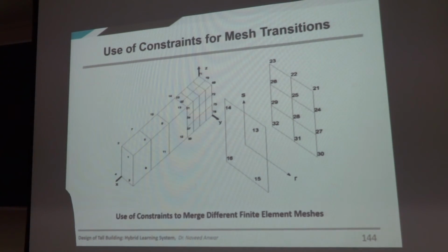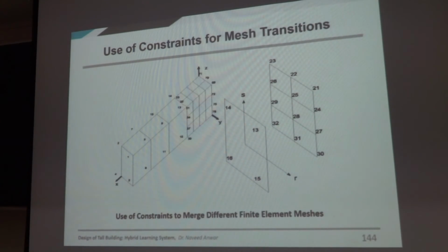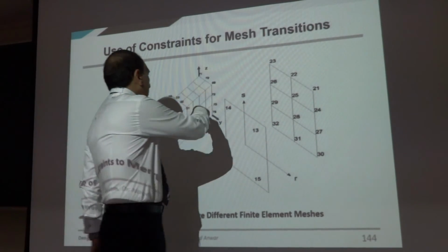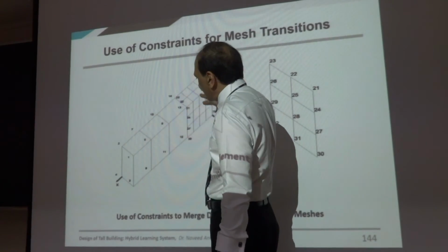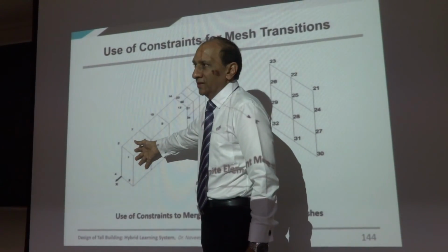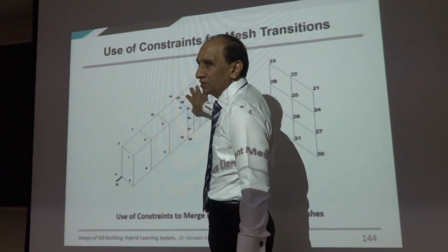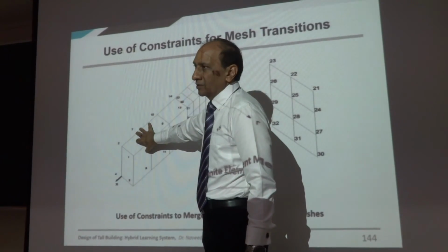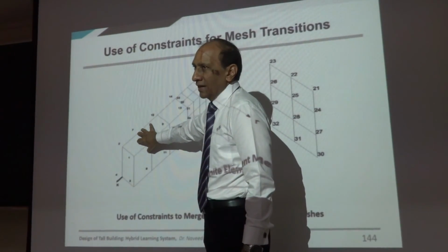So I chop it up into small pieces, Lego pieces, because I want to understand what's going on inside the beam. Not only the overall bending moment, I want to calculate stresses deep inside, strains and everything. So I will model it by solid element. And I am more interested at the corner or at this location and not interested so much there. So here I want a fine mesh. Here I don't care about the mesh so much. I just want to model it.